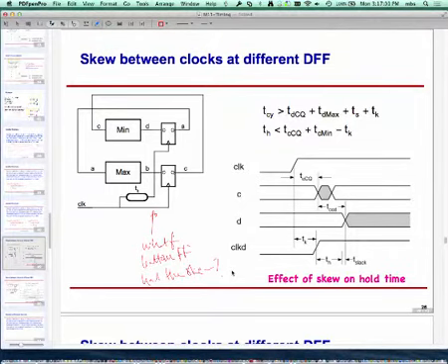So clock skew, because of this wiring, is another issue. Wires have delays. Wires have significant delays. Ultimately, information cannot travel faster than the speed of light, so once you are into picoseconds and tenths of a picosecond, even the speed of light matters. And wires are not just transmission lines.